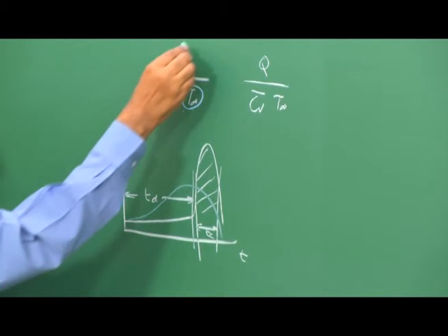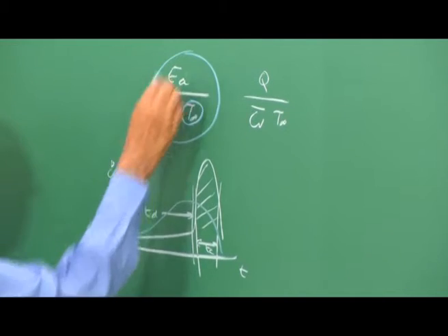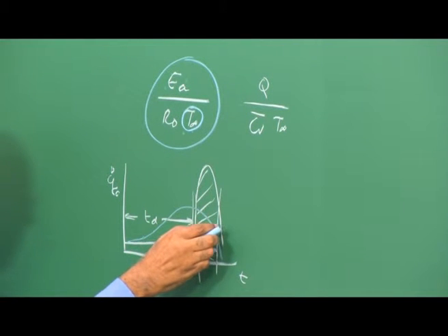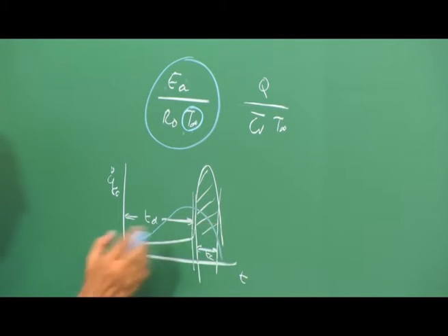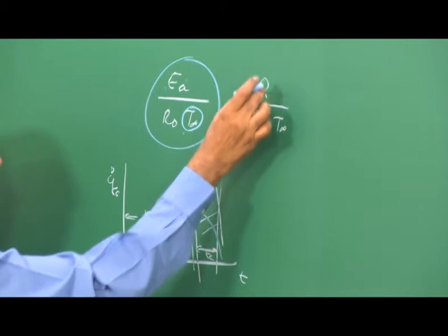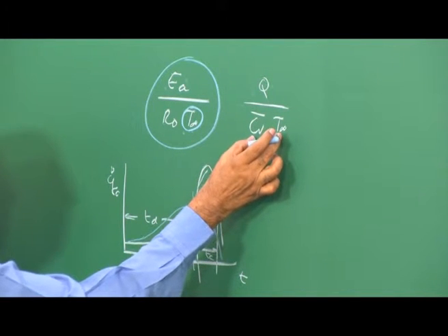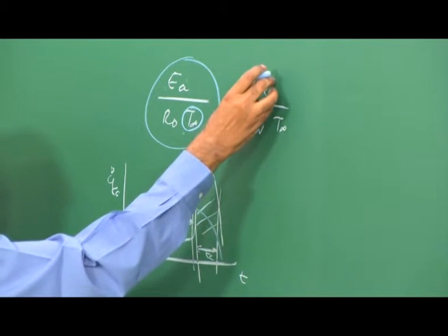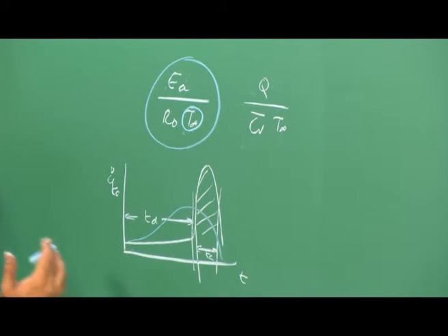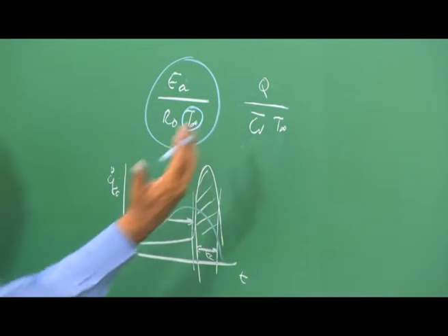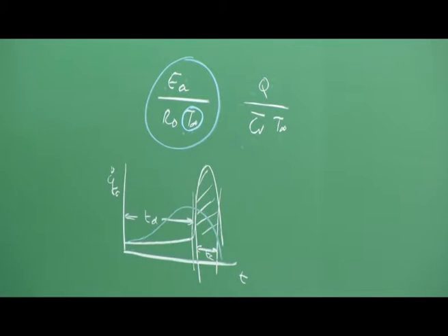Now, this is the non-dimensional parameter which characterizes the spurt in chemical reactions, or spurt in heat release after an induction time. This term tells you the magnitude of heat release vis-a-vis the initial internal energy of the medium. If I have more energy release, an explosion is capable of forming a strong blast wave. These are the two parameters.